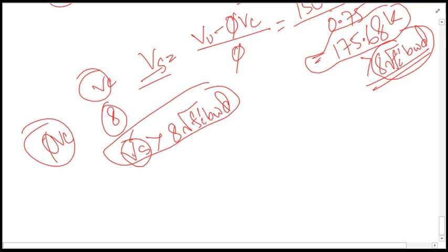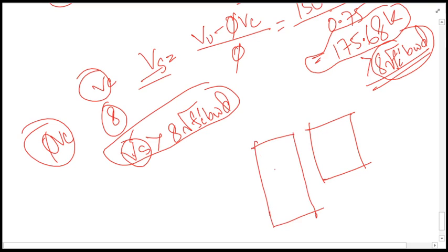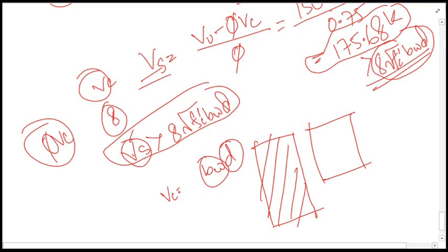And that's why, although we can overcome this with the shear reinforcement, the code says no, you cannot provide this; rather you will have to change the section. If you change the section, the beam dimension, if the width or depth is increased, the area will be increased. And that's why in the VC formula, there is bwd, and if you also increase the strength of the concrete, root fc prime, all these three in combination, the VC will be increased.